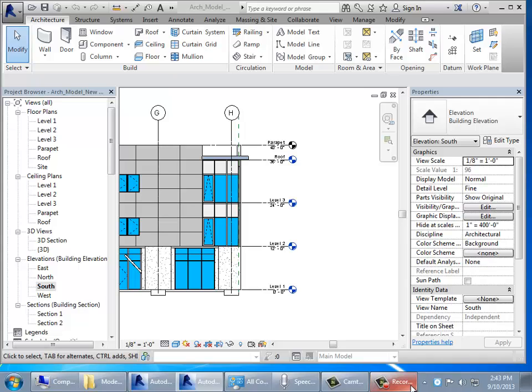Okay, so that's why I say, before you put a whole lot of time into the doors, walls, windows, and stuff like that, get the levels, get the grids in there. You just gotta think about your scheme. Now, I tend to work with a fairly simple scheme, just these top of slabs. Some people will put the ceiling level in there and the floor levels in there. You can put all sorts of intermediate reference points, some hat height or some intermediate level with equal height, reference levels or reference lines to it. Okay? But I think keep the levels pretty simple.